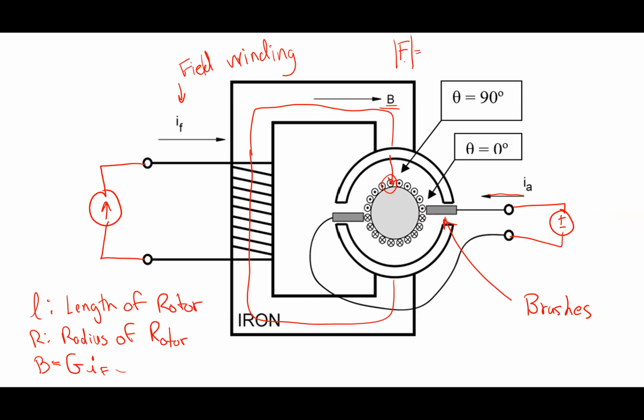So it's I L cross B, right, is my force. What's the cool thing about L cross B here? It's 90 degrees. They're normal to each other. B is coming straight down, I is going out, so they're 90 degrees to each other. That's because of the boundary conditions and everything. The B field and the current are always going to be 90 degrees separated from each other. That means the magnitude is just I, L, B, and specifically, it's I sub A, like that. You guys follow that?